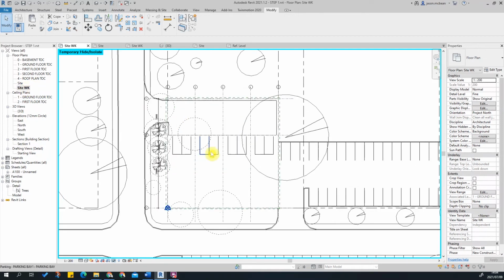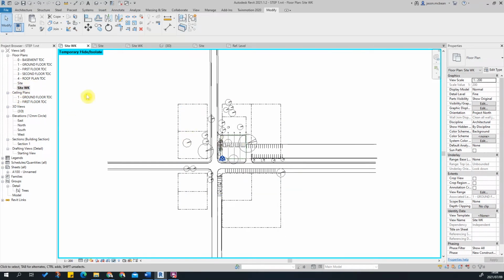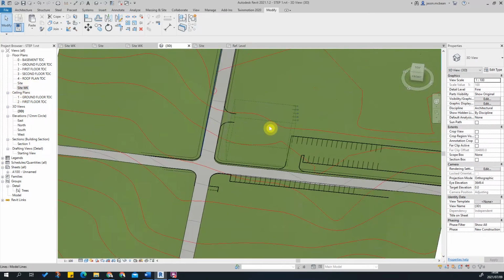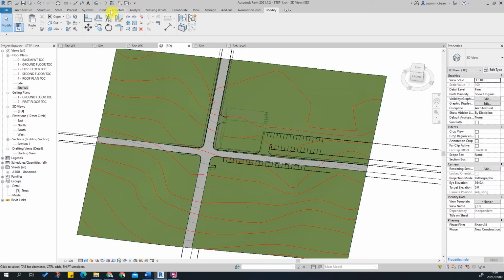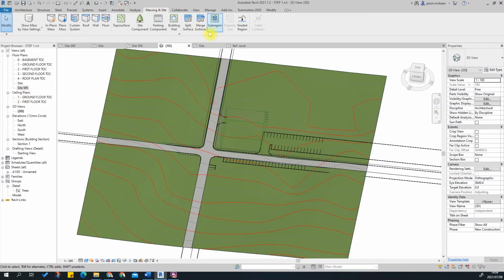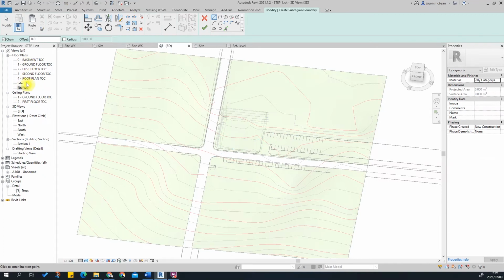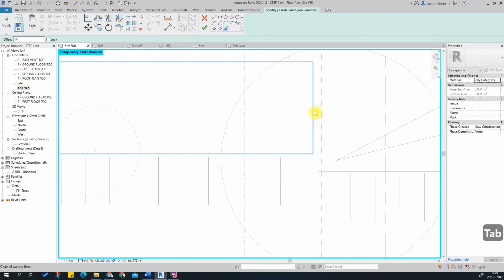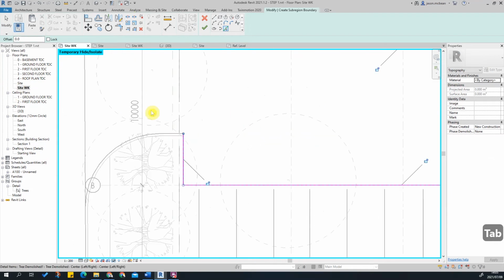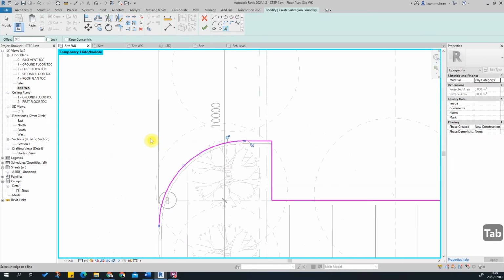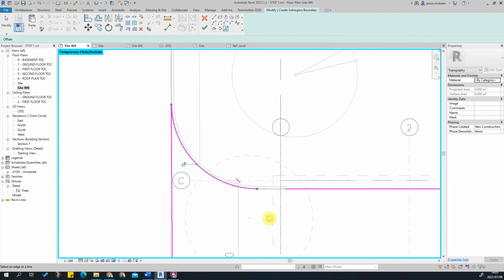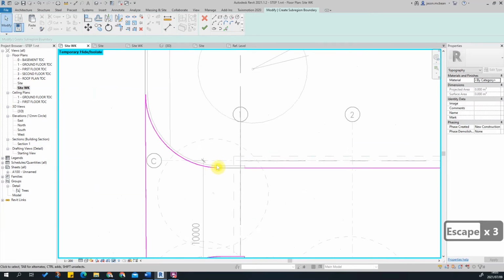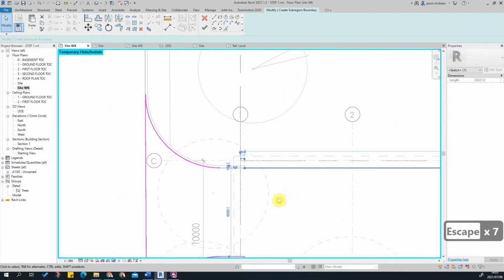Let's just go to my site. Go back to 3D view. You're going to select the tool here called massing and site. You're going to go sub-region. Go back to site working, because this works through all of the, select this layer, press tab. Then all you've got to do is just finish off this line work. Press escape, select that pink line, go isolate category now.